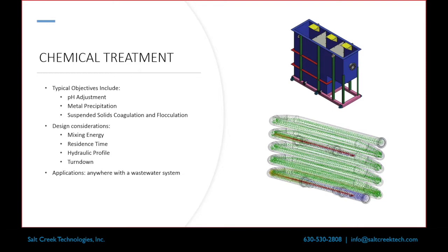That's one of the benefits of a tank system. You can have a little bit more flexibility as far as I'm going to have a high-speed mixer in the front end to put a lot of mixing energy into the system. I can size that tank to have a slightly larger or smaller residence time.